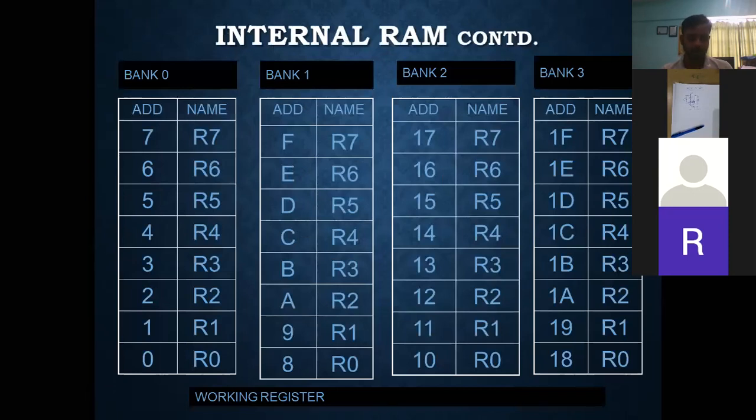Right. But whenever we are writing a program that uses multiple banks, we need to initialize the bank every time before using it. For a small program where many registers are not needed, if we do not initialize RS0 and RS1, then one or two lines of the program are saved, so the program length will be decreased. That is the thing. If you are writing a long program, adding two or three lines will not matter much.